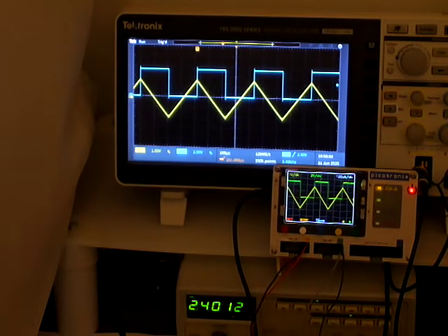time base. Okay, so time base allows us to select the time per division. So what this will do is that in the signal processing, Pico will actually process the contents of what's captured by the ADC in a different way, and in the case of slow time bases it will have to decimate the large number of samples, and in the case of higher sample rates it will actually interpolate so we get a decent sort of a signal.